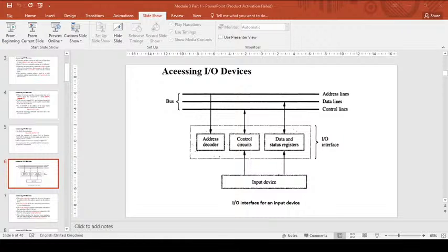So in this particular example, in this program, we have again discussed program controlled IO, right? We are continuously monitoring the SIN and SOUT status flags, and depending upon the condition of that, the data is read and displayed by the processor. This is again a similar program you have studied under module 2, very similar to this, right? So that was the example for program controlled IO, reading the input device, writing onto the display device by continuously monitoring the status flags SIN and SOUT.